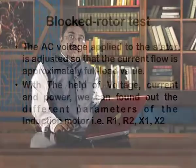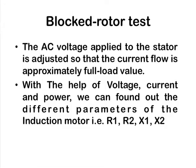Mind it, in case of the no load test, rated voltage is applied, but in the blocked rotor test, rated current is allowed to flow. With the help of the blocked rotor test, we can find out the stator and the rotor parameters. With the help of the measured voltage, current and power, we can find out the equivalent circuit parameters R1, R2, X1 and X2. Thus, by combining these three tests, we can find out all the equivalent parameters of an induction motor.